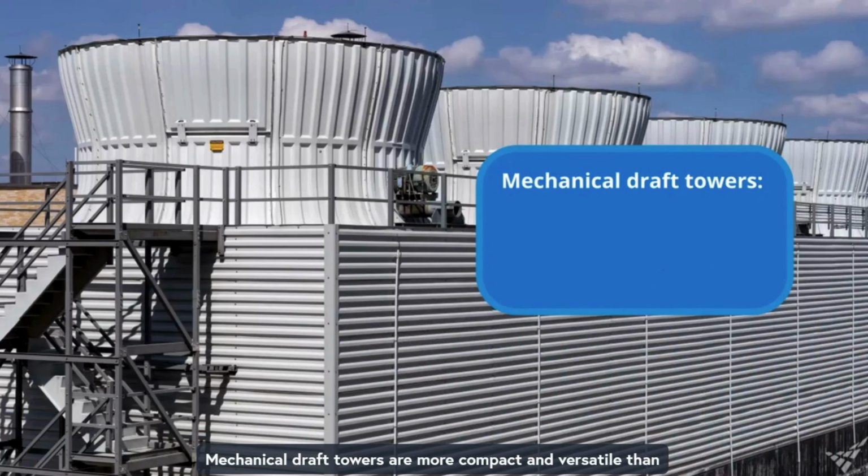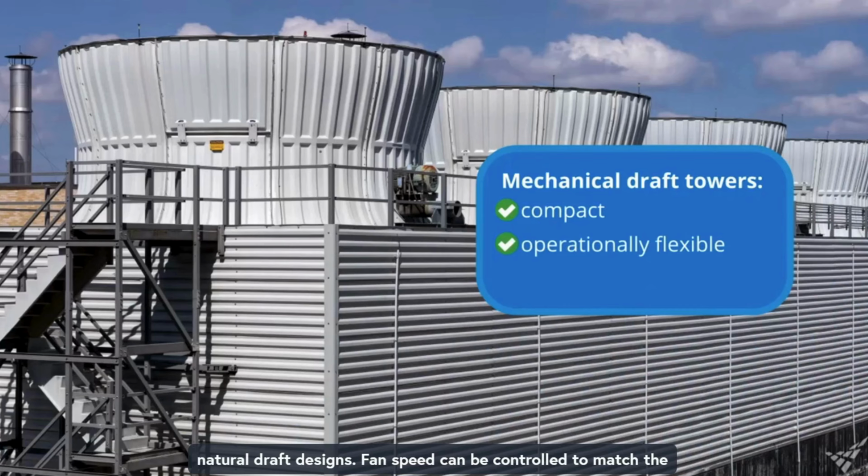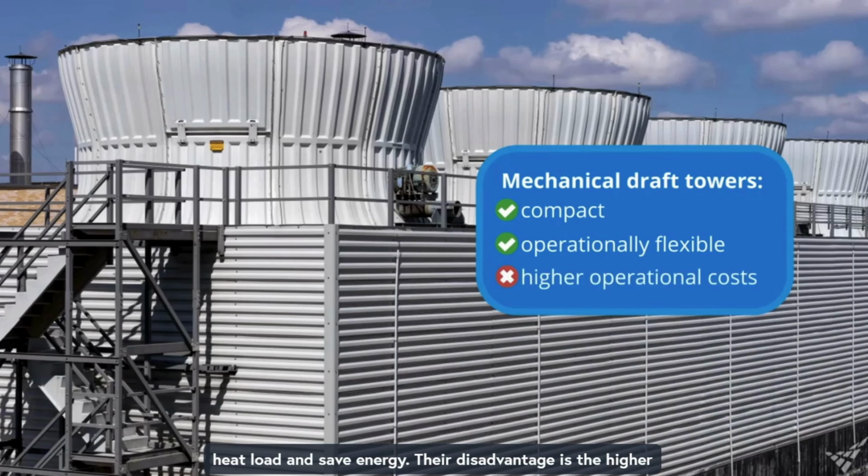Mechanical draft towers are more compact and versatile than natural draft designs. Fan speed can be controlled to match the heat load and save energy. Their disadvantage is the higher operational costs incurred by the power requirements and maintenance of the fans.